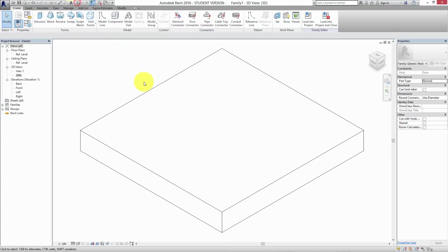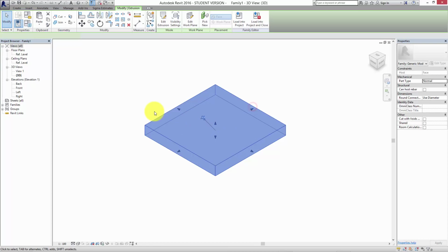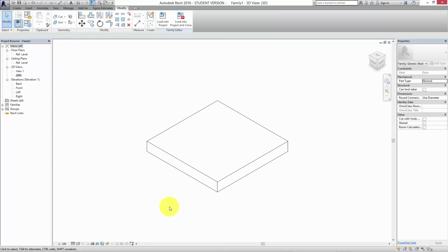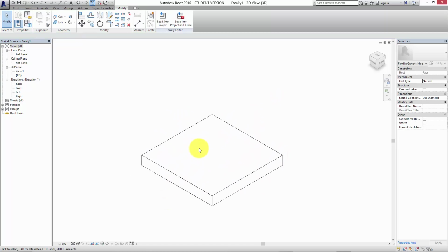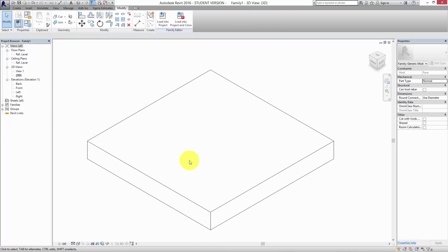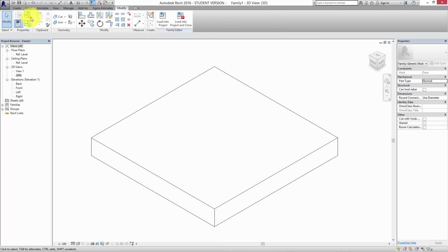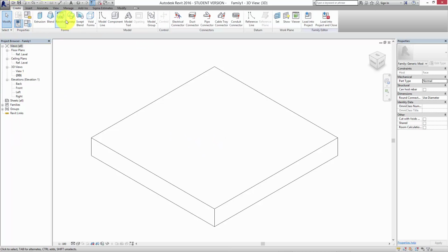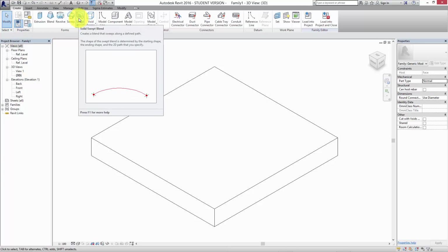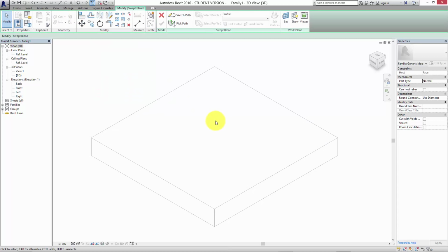And if I show you what this is, it's giving us a kind of a wall just as an idea as to where we're going to put our element. So to make the shape we want, which is kind of a right angle triangle, isn't it? It's like that, yeah. And we want to stick it on the side of the column. So I've got to use this swept blend option here, solid swept blend, which allows us to take two shapes and then make a 3D model between them.